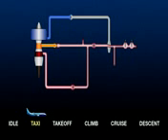Depending on throttle setting, the pressure may rise above 32 psi. If this happens, the HSV will act to regulate the pressure to 32 psi. Again, depending on throttle setting, the bleed air temperature may rise above 390 degrees Fahrenheit. If this happens, the PCCV will open to keep the bleed air at 390 degrees or below.